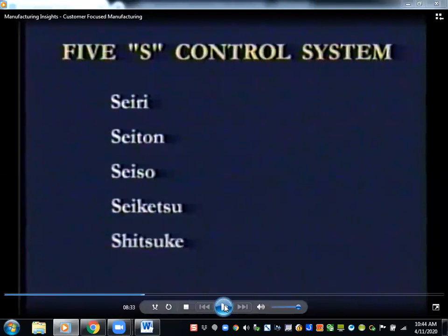If I may break from the speaker, personally, I believe that 5S should come way in the beginning because only when you do 5S, and remember from a previous lecture, there are three questions you ask about every item that is going to go into the cell. Do we use it every day? Well, keep it at the point of use. We do use it, but we do not use it every day. Keep it inside the cell, but on the periphery, so it can be accessed whenever it's needed.